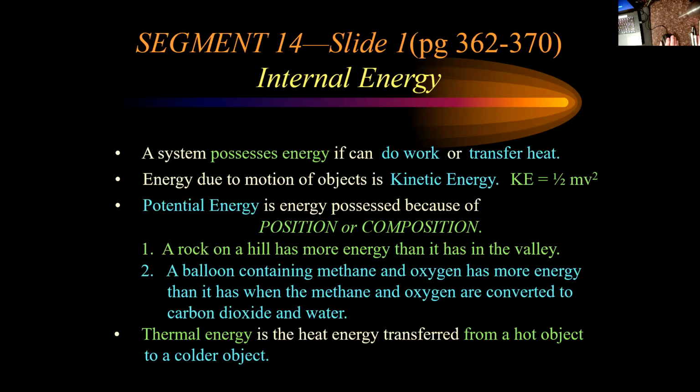So you've got to have a hot and a cold object to ever transfer thermal energy into any kind of work. And in Gen Chem 2, I'll tell you the very simple equation that you can use to predict what percentage that is. I'll tell you here. If you took the temperature of the hot object in Kelvin and the temperature of the cold object in Kelvin, subtract the two, and then divide that by the temperature of the hot object, that's the fraction, multiplied by 100 it's the percent of that energy that gets transferred into work. T high minus T low divided by T high.